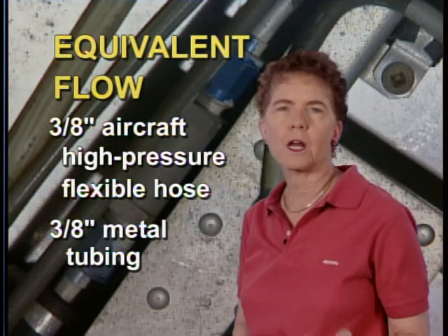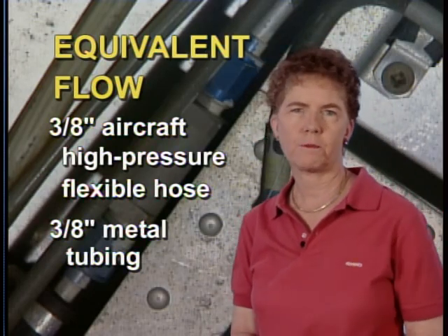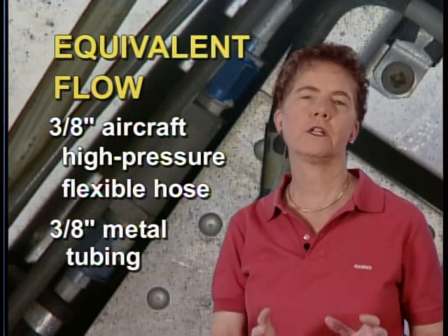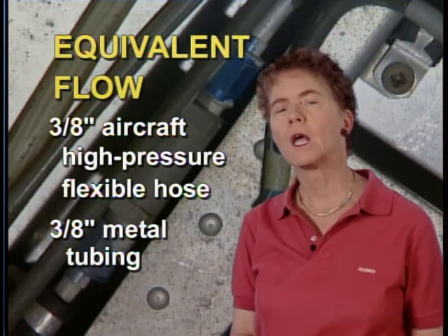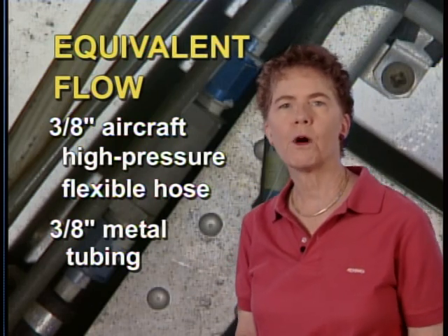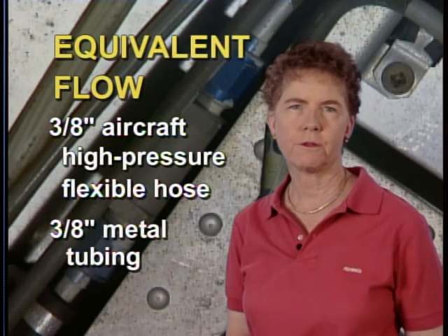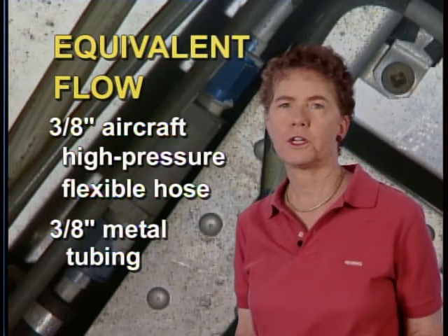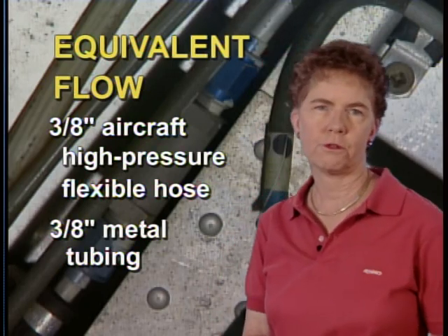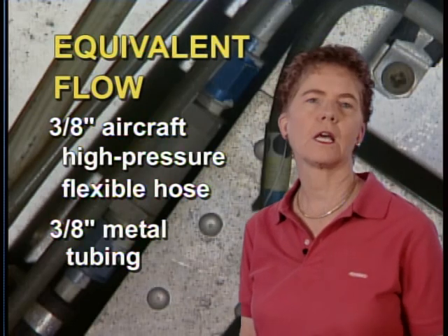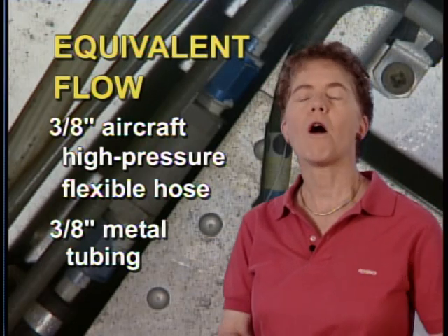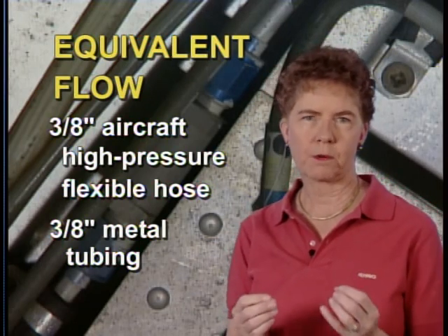Now, it's common for an aircraft fluid system to have both types of lines. Rigid metal tubing is used when it can be attached to non-moving structural portions of the aircraft. However, flexible hoses have to be used in lines that connect a component that moves or vibrates relative to the aircraft structure. That's a situation that would break a rigid metal tube. Flexible hoses are also used where a line has to be repeatedly connected and disconnected. So flexible hoses and metal tubing rarely have interchangeable applications.